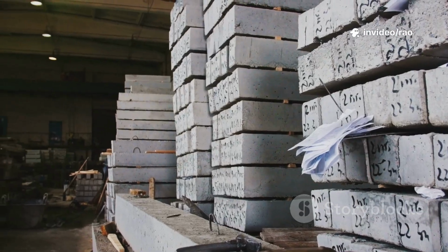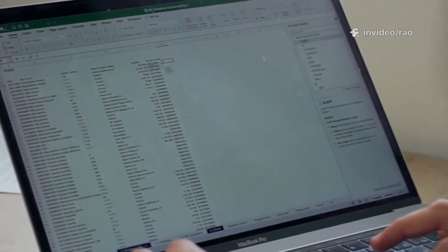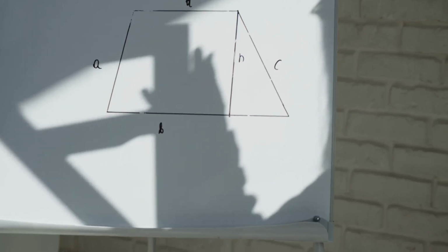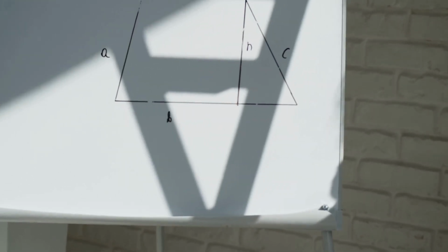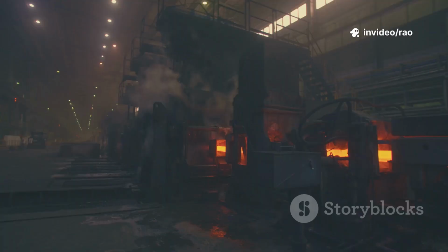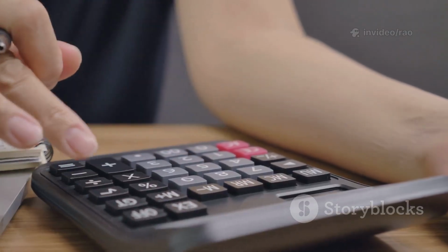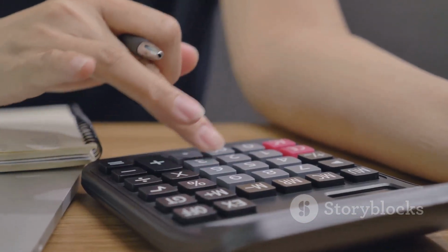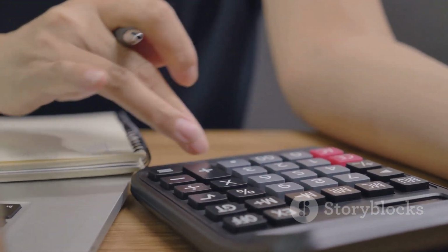Now, distribution bars. Distribution bar length equals 3 m, i.e. 3000 mm. They run across the slab length, equals 4 m, i.e. 4000 mm. Total distance equals slab length. Number of distribution bars equals 4000 mm divided by 150 mm, plus 1. Number of distribution bars equals 26.67 + 1, equals 27.67.